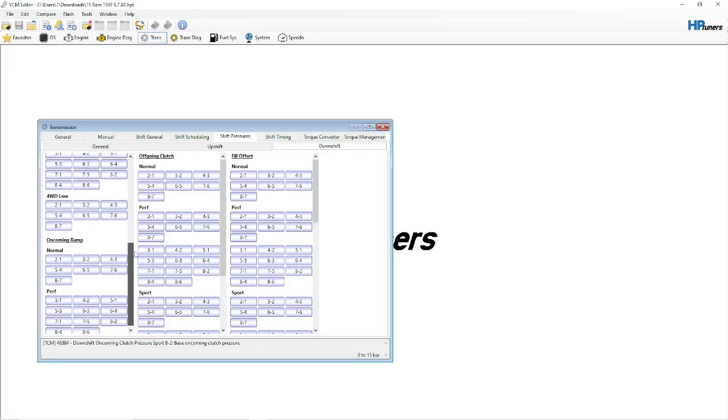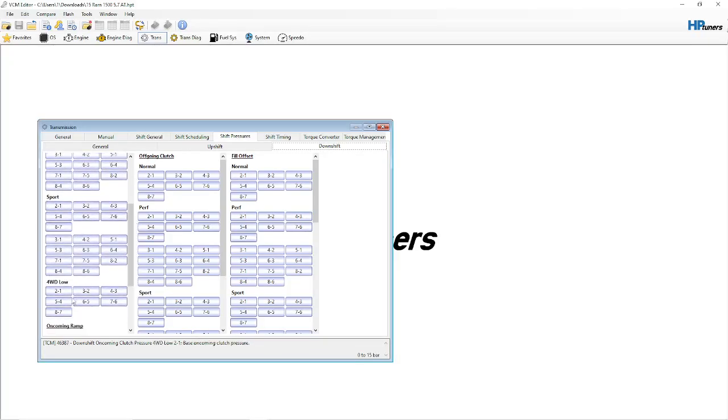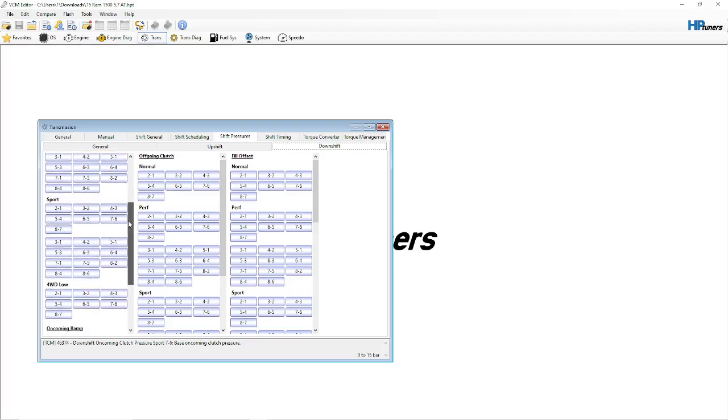So, for demonstration purposes, we're going to say the sport is the towing, because most of these vehicles do have a towing feature. Same exact thing. We want to try to build that low end torque, but we want to do it safely. We don't want to exert too much on the actual components of the drivetrain, because then you may break things, especially if you have something heavy, or if you smash your foot in it a little bit too fast, things like that.